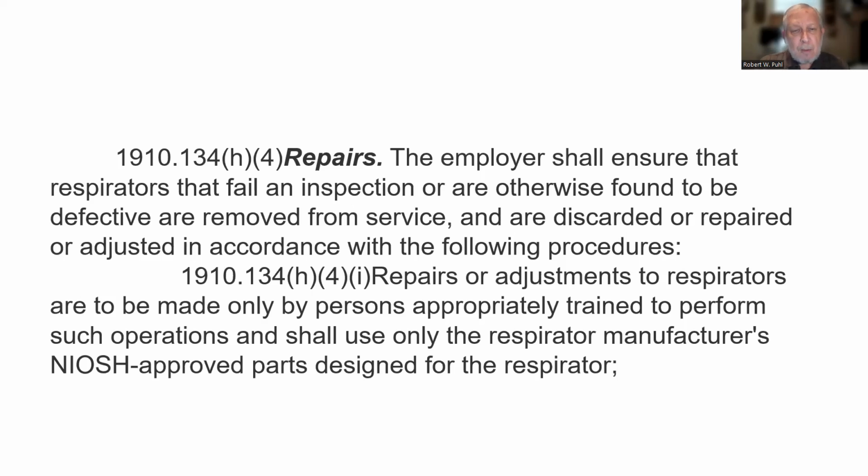The employer shall ensure that respirators that fail an inspection or are otherwise found to be defective are removed from service and are discarded or repaired or adjusted in accordance with the following procedures. Repairs or adjustments to respirators are to be made only by persons appropriately trained to perform such operations and shall use only the respirator manufacturer's NIOSH-approved parts designed for the respirator.